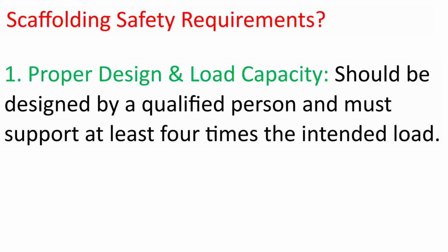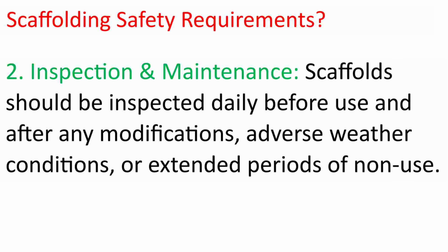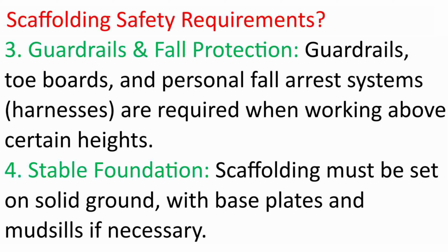Question: what are the scaffolding safety requirements? 1. Proper design and load capacity. Should be designed by a qualified person and must support at least 4 times the intended load. 2. Inspection and maintenance. Scaffolds should be inspected daily before use, and after any modifications, adverse weather conditions, or extended periods of non-use. 3. Guardrails and fall protection.